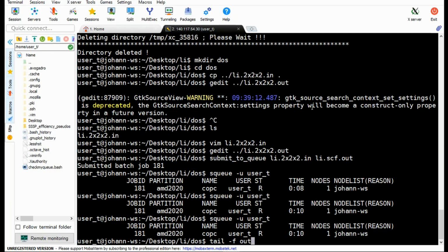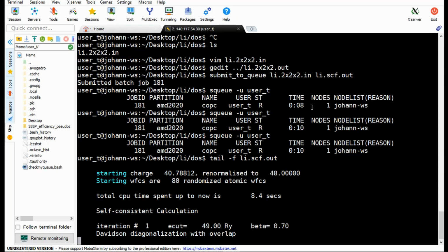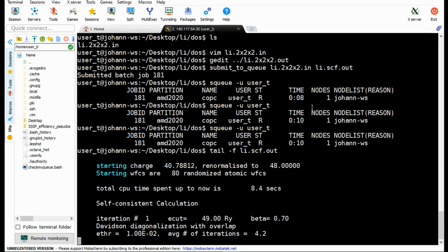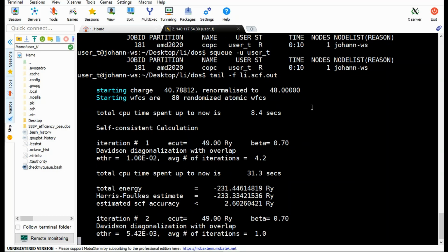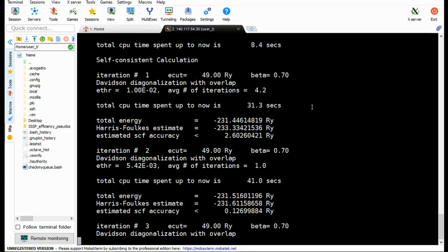But you have done that before, right? This small repetition is just to see if you have done things differently or not. So far so good, right? You optimized your structure, volume relaxation plus atomic position relaxation. Then you look if your structure looks okay. You open and visualize the structure, you turn it around.